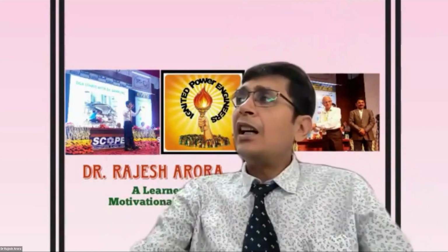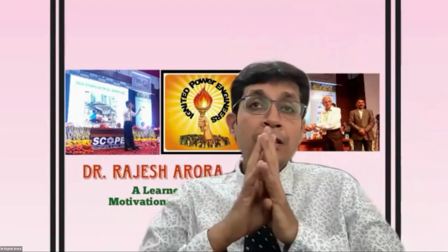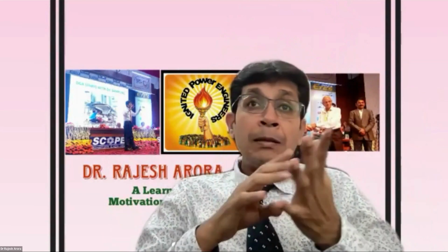One more thing, sir. One of the engineers from AP Transco, Deputy Executive Engineer QC, Mr. Hari Prasad, has asked: what are the recommendations for a transformer that has served more than 20 years? Okay. When your transformer has already lived its useful life of 20 years, you have to do proper condition monitoring of your transformer. That includes your tan delta, that is a very important thing.